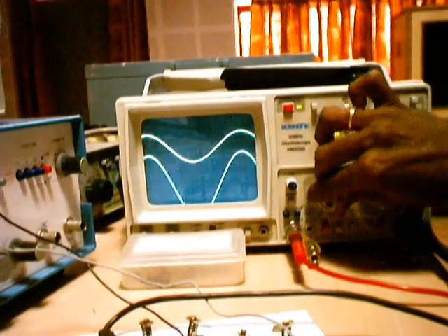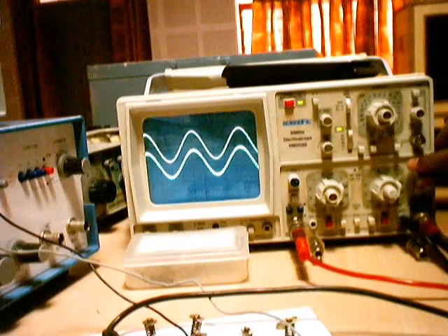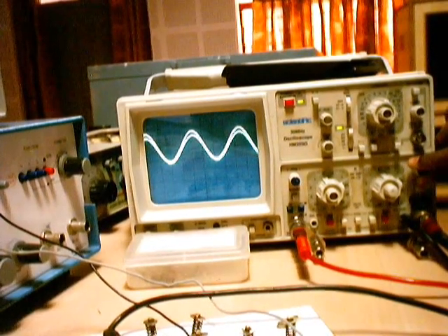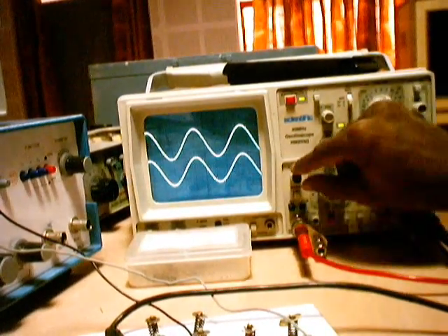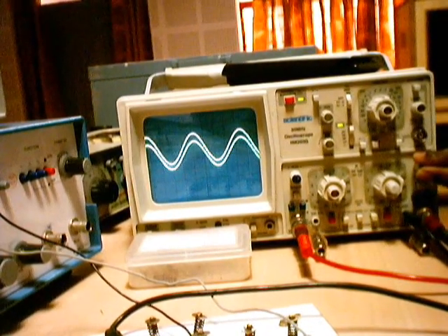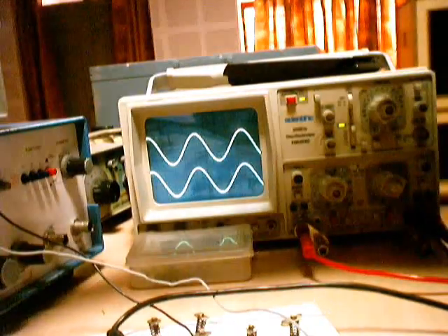You can see it over here. Both are at 5 divisions. You can just coincide both of them. You can see their amplitudes are almost the same. This is also 5, this is also 5. This is your input, this is the output. Both amplitudes are almost the same because I'm in the pass band of the band stop filter.